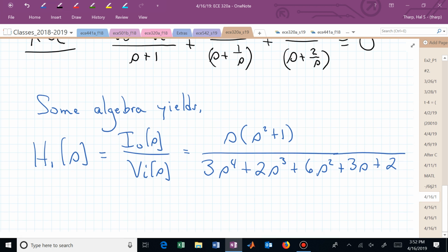Where are your zeros located in this transfer function? And I ask that because one of them is not very hard to find. It's at 0, isn't it? You're looking at the finite values of s that cause the numerator to vanish. You have a 0 at s equals 0, or a 0 at the origin. And where's your other? What values of s cause this s squared plus 1 to vanish? Plus and minus j, isn't it? So now you have 3 finite zeros.